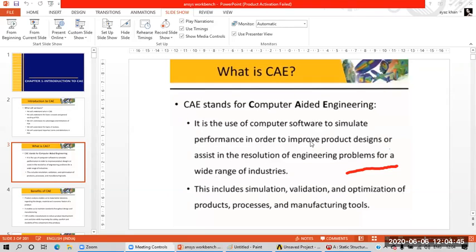Okay, sir. But right now, I will tell you in brief, when you are analyzing something, the most time-taking procedure is your mesh generation, the meshing. Yes, sir. That takes the most time. Other things like calculating results or making the physical model, that is not the case, but mesh generation is a very time-taking procedure.